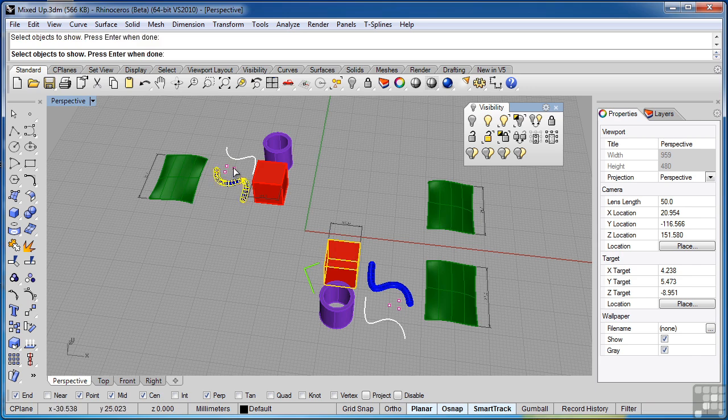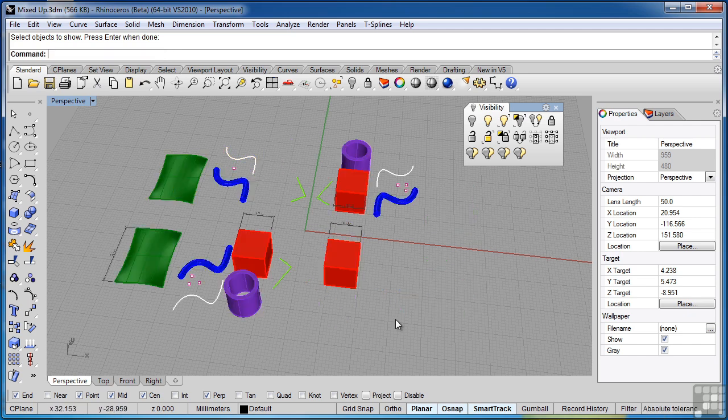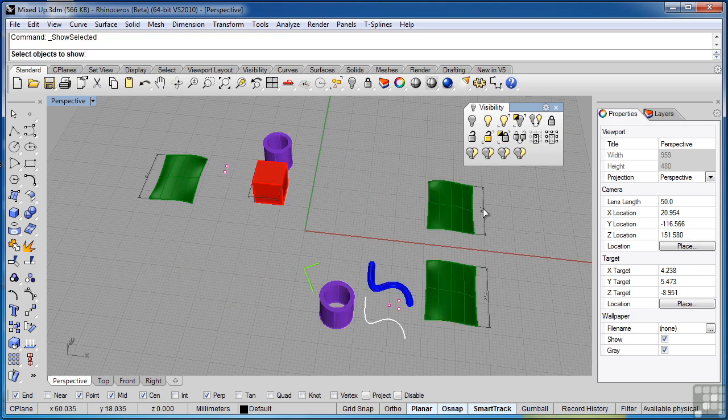And by selecting on objects, again, we can choose curves, control points, surfaces, polysurfaces, dimensions. Anything that's selected when we hit enter will now unhide. So when I press enter to apply the command, you're going to see the display changes again, and it's going to show us all of the parts that are unhidden, including these new parts that we've selected to unhide. So now that's brought back all the parts that we selected and added them to the group of parts that was already still visible.